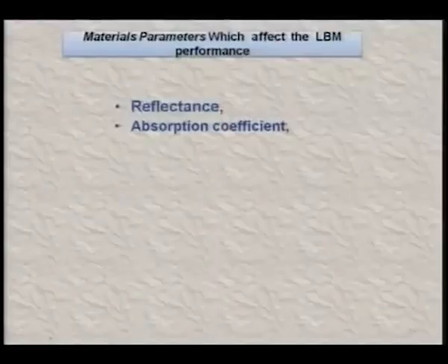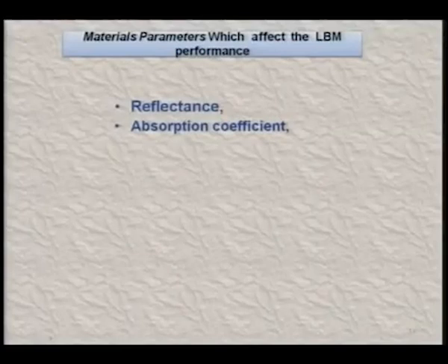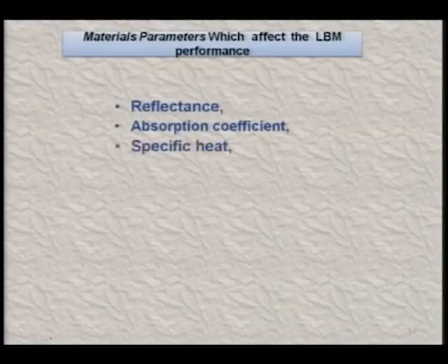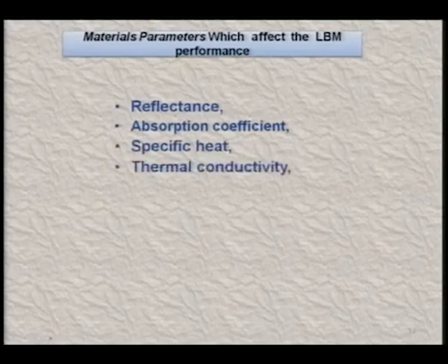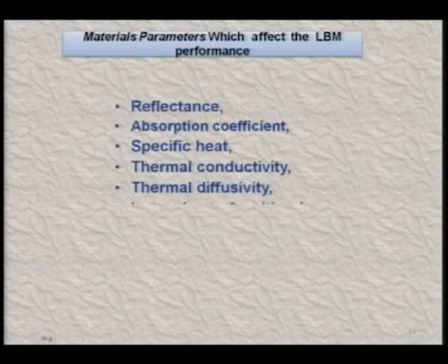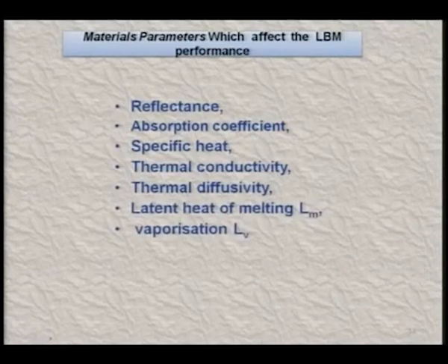So, we should consider properties of the workpiece material such as reflectance, absorption coefficient, specific heat, thermal conductivity, thermal diffusivity, latent heat of melting, latent heat of vaporization,